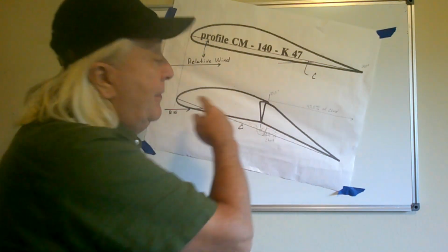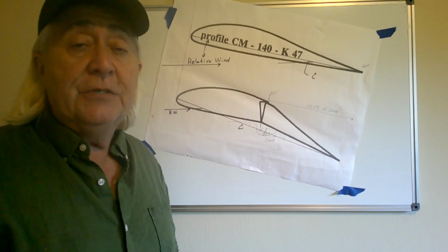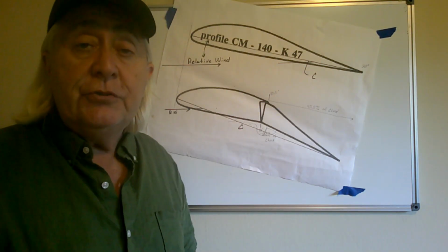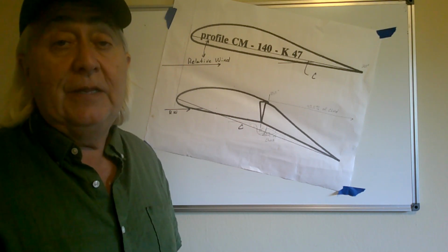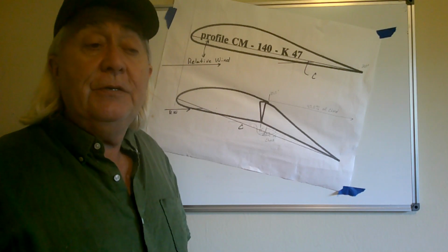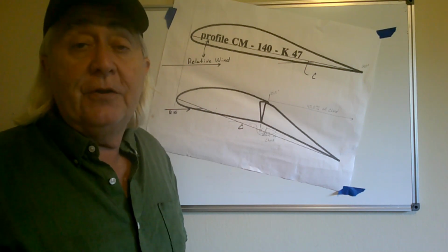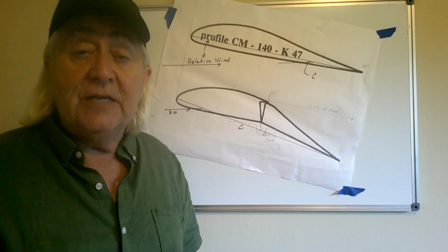Any further forward than that, you're ruining the performance of the airfoil and putting yourself in danger of inducing a stall due to control deflections. And that's all there is to it. I wish I had a smoother answer, something more exciting, but I don't. It's just a stall. We know what not to do. At least we have a solid lesson learned.